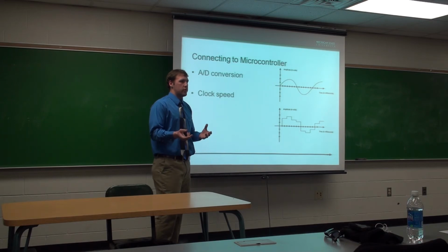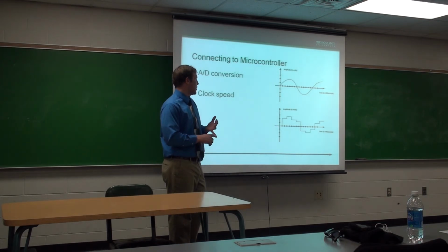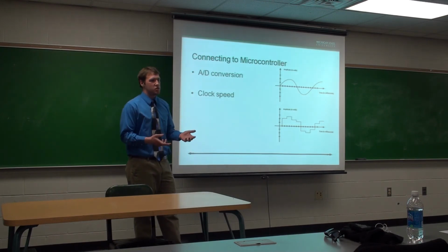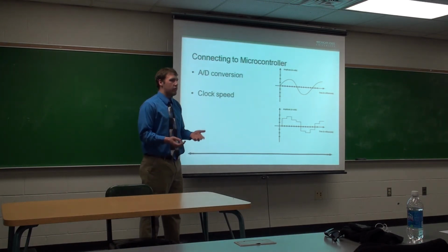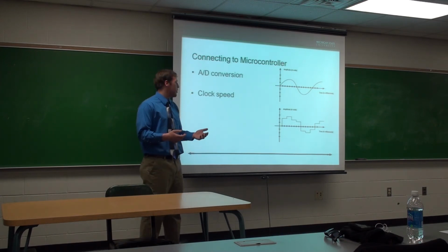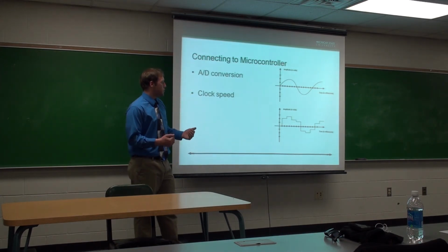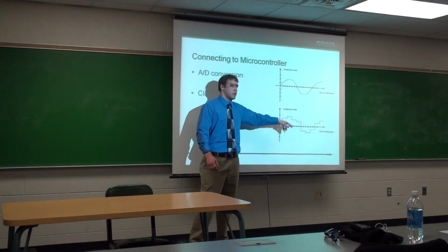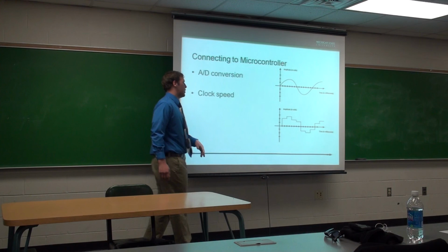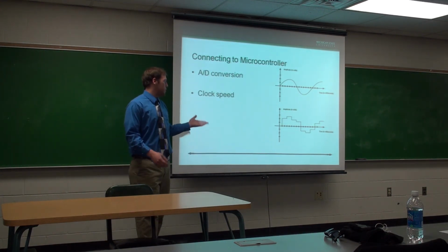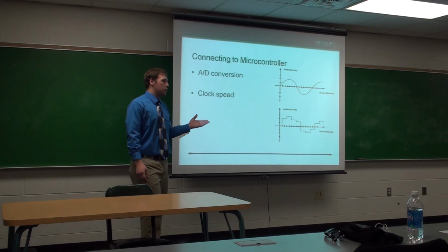the clarity of your signal, as well as make it economically not viable. The file size may be too big, the bit stream may be too long, so you could have other errors that are introduced unintentionally if you choose your sampling rate too high. If you choose your sampling rate too low, your quantization levels may jump drastically, and your signal may not be mimicked very well. So we tend to use a sampling rate known as a Nyquist rate.